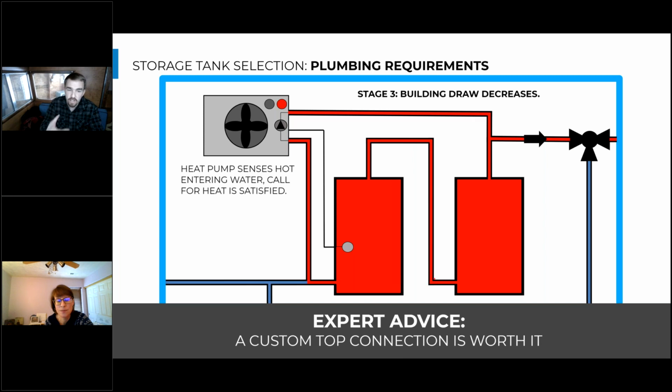If you have a separation of hot and cold volumes and your 140 or 150 degree water has worked its way down to 3/4 of the way down this first tank, you're still like 7/8 full in your full storage capacity.